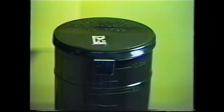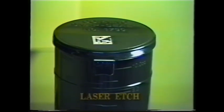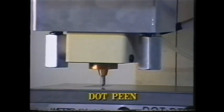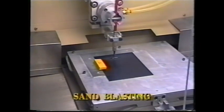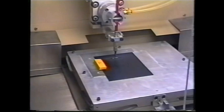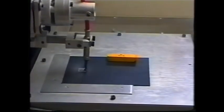Laser etching is the most versatile method for marking the Vericode symbol. A high-intensity focused beam of light literally vaporizes a thin layer from the surface of the material, creating the image. The dot peen directly marks the material by creating a series of small indentations in the material surface. Microabrasive blasting is a non-contact process that uses fine abrasive particles propelled with a stream of air through a small nozzle tip to engrave the Vericode symbol directly onto the material surface.